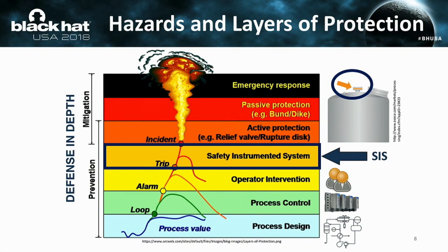After that, if safety systems were not able to prevent the incident, we already have an incident. Then the last hope is, but we already have an incident, we still can have, like, a rupture disk in the design of mechanical vessels, for example, and some release valves, mechanical valves which just open by their own. But we already have an incident. Therefore, safety instrumented systems are important.